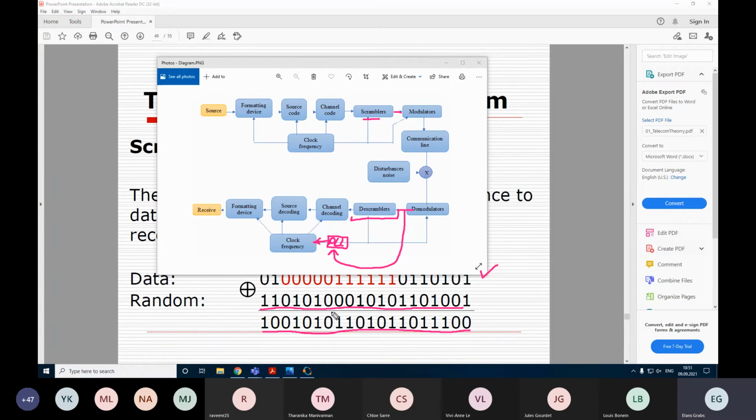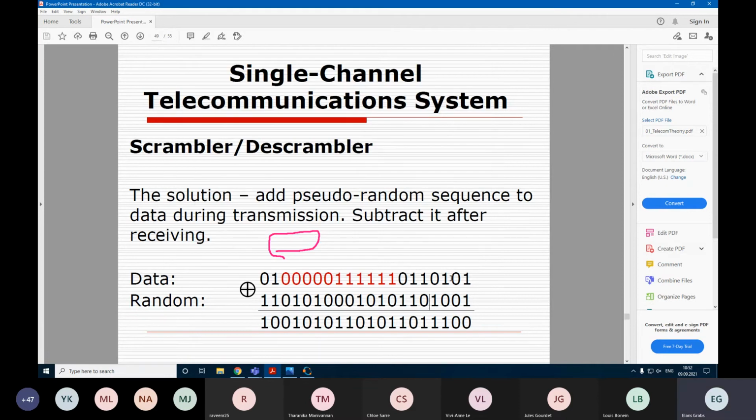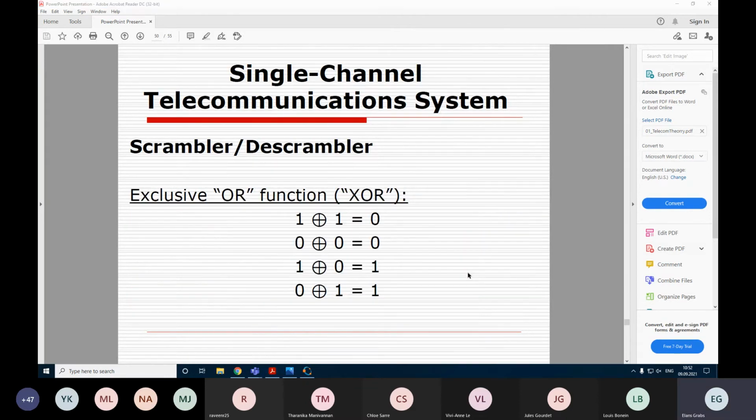You most probably already know that there are pseudo-random number generators, and one of these generator algorithms is the M-sequence generator. This is one used in scrambling. So these two blocks generate the very same sequence. This adds the sequence, this subtracts the sequence, and our data is left again as original data. In the meantime, this clock generator is being adjusted, and this way we solve the problem of synchronizing.